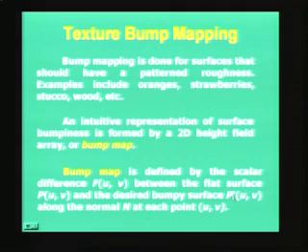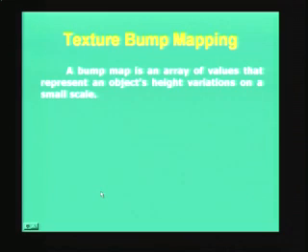The desired bumpy surface p' is a random variation of (u,v) along the surface normal, and that sits on the flat surface p(u,v) and creates your f(u,v), the final bump map. So, you talk of a layer p(u,v), another p' sitting on p, and that creates your f, the bump map. We will see examples as we go along, but let us read a few more concepts.